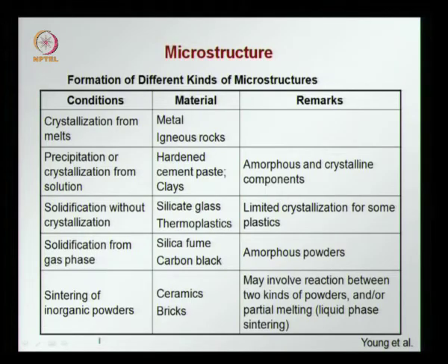We can have solidification occurring from the gas phase also. For example, in the case of silica fume, carbon black, these are amorphous powders. Silica fume you would have heard of is a material that is very useful in concrete, because it has a very high silica content and it is amorphous.